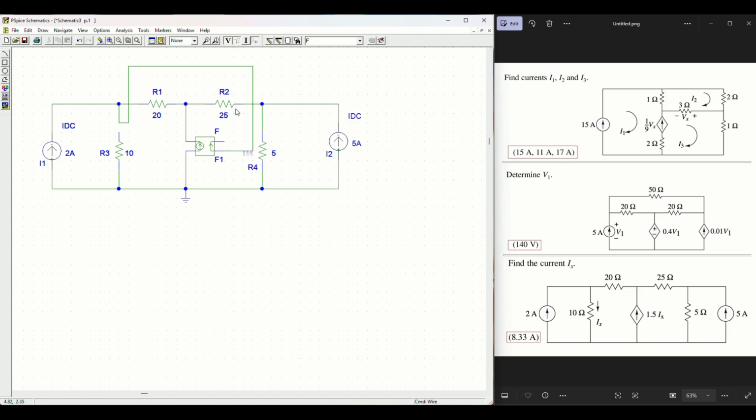Whenever we are just crossing this resistor at that first point, that is why we are getting that node, because the system is considering that this resistor should also be connected. But if you put it slightly further away, then the connection is not getting aligned. So the current will come here, it will move to the dependent source.